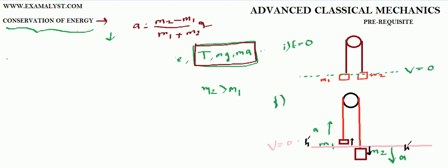So we know through what height the mass has moved and what the acceleration is. How to calculate velocity? We know that v square equals 2 into a into h dash. Okay, you all know this equation. So this is the velocity of both the masses if they have moved a distance h dash with acceleration a. That means the velocity of both the masses will be root over 2a h dash. Agreed? That's part 1 of the theory.